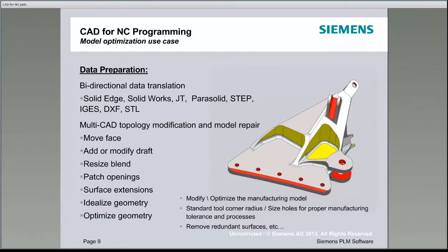And when we go back and we look at the drawing for this part, and there were tolerances like ±5 on some of these blends, we could redefine those blends as being a common tool nose radius, right? So we could go and find a standard 8, 16, 32nd, whatever our ball nose radius to match that. So we don't have the scallop and surface repair, polishing, etc., that would have to go into these models. And so that's what we really say is about optimizing them from a design standpoint.